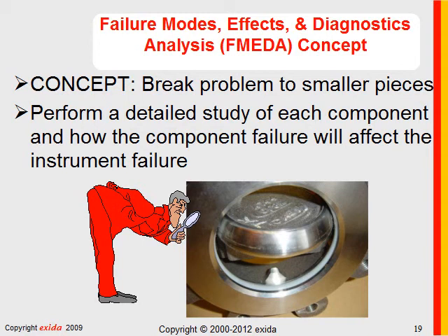Then if a new design comes along using the same components, you can use the technique of simply analyzing the reliability network of the product. For the most part, it's a series system where any component fails, the product fails, and generate a failure rate for a brand new design. It's the same concept used in the old Mil Handbook 217, which was created about 40 years ago.